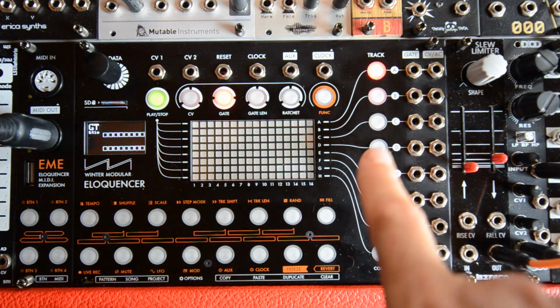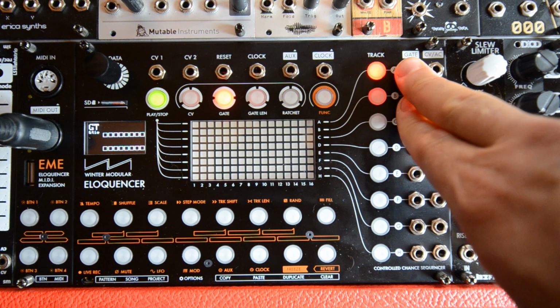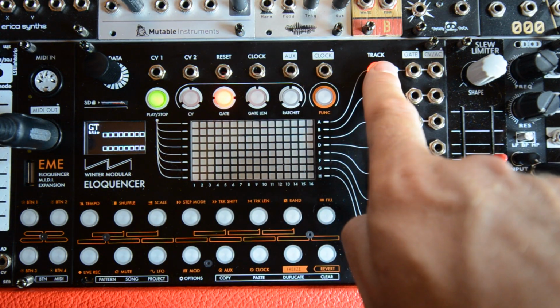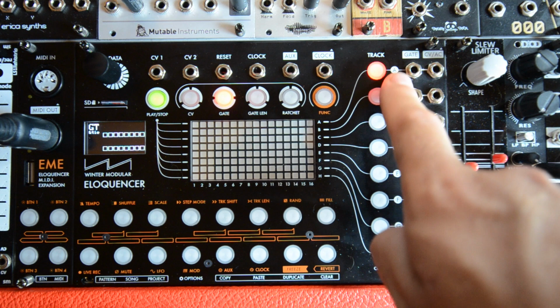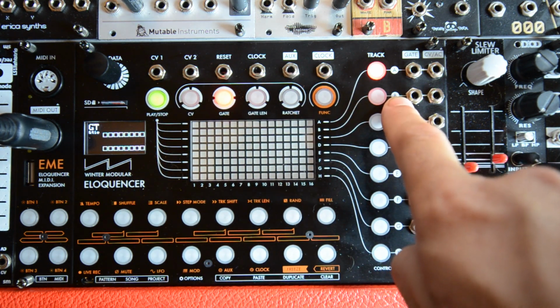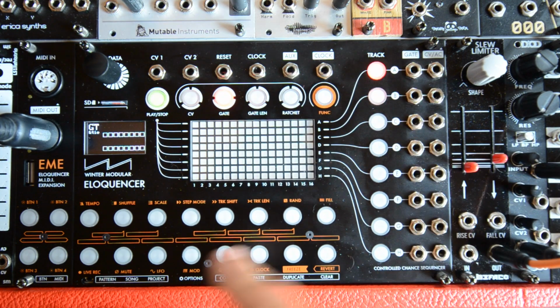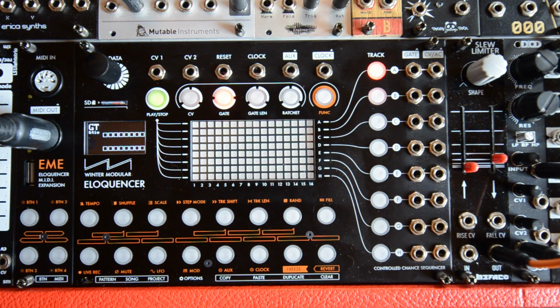We also can combine 2 tracks to have pitch and velocity. For example, the CV information in track A can be used to send information about the pitch, and the CV information in track B can be used to send information about the velocity. So the two tracks are combined to send a MIDI message that controls when a note starts, when a note ends, and the pitch and the velocity.